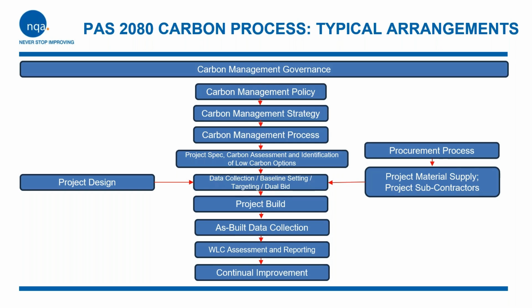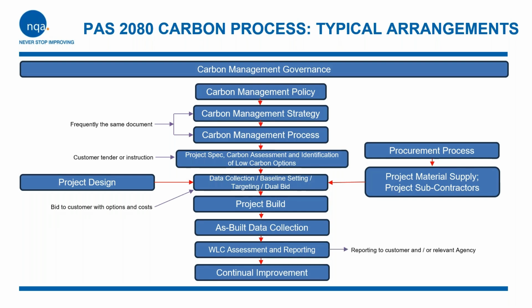And we then have the project build itself, and then once the build's complete, there's a process of pulling together as-built data, the as-built carbon data, that is, and then that can be compared to what the original baseline was, what would have happened without the intervention of the whole life carbon management. And then once the as-built carbon data is collected, that enables the whole life carbon assessment reporting side of things to take place. And sometimes there's a requirement to report back to the customer and perhaps the relevant agency as well.